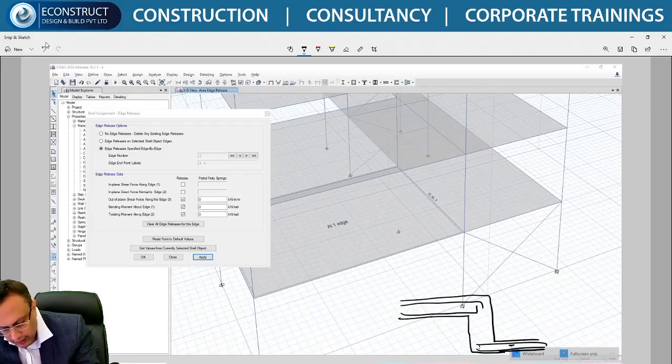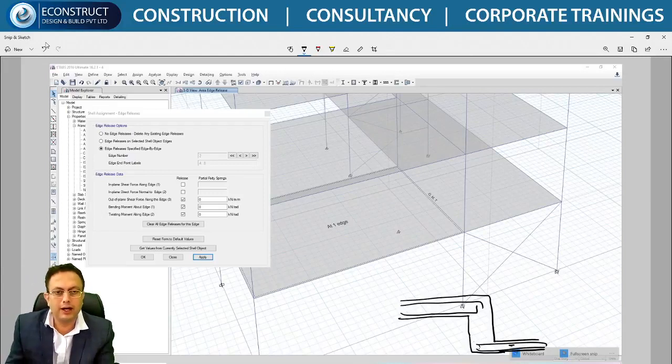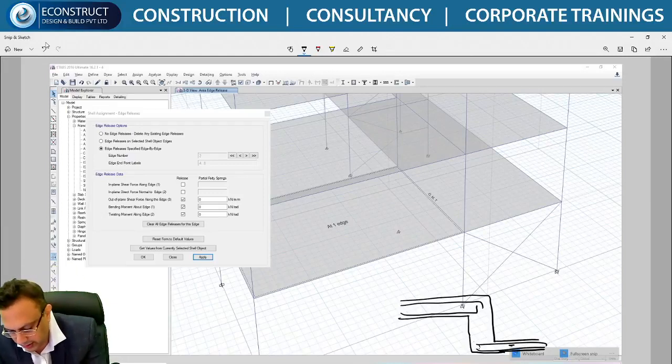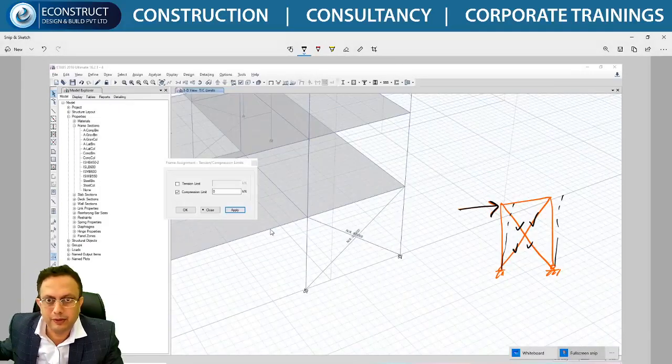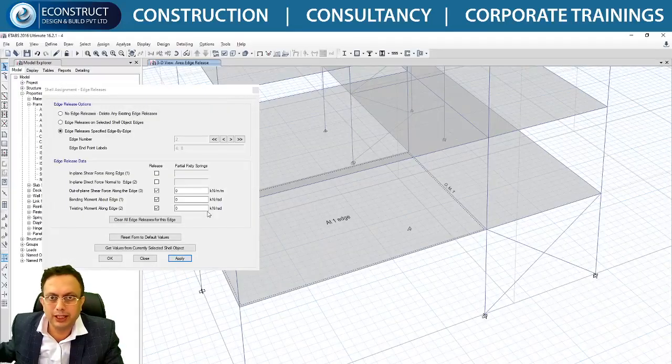So the kind of arrangement that we need to do over here is, this slab will be having the release function here, and this slab will be having the release function here at this edge. So like that, what we have given like this over here. In the model it will be at one plane only, one edge only, but you will give the mathematical release at this function like this. Understood? You just need to practice this so that it will be very helpful for you.